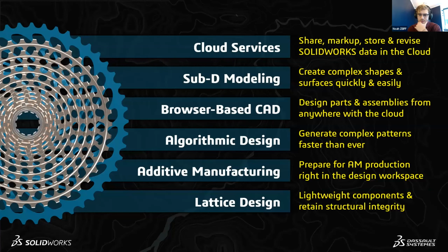Thanks for getting that one, Gian. I see one here from Zavin. Additive manufacturing requires CAD file input in STL. Is this automatically done with a feature? Yeah, anytime you're ready to 3D print any components from either SOLIDWORKS Desktop, 3D Experience SOLIDWORKS, or the cloud, you can export in STL. You could also edit the number of triangles you have on an STL to see how fine your file is if you really want those clean curves, or if detail isn't as important, you could lower that so it's more faceted. That way your STL file is a lot smaller. You have control over all of that.